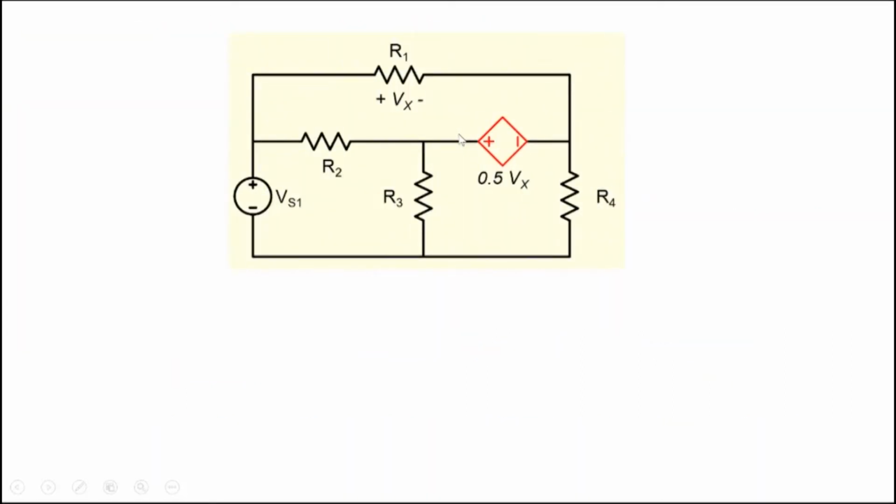Well, let's look at a case where we have a dependent voltage source. The dependent voltage source will make it floating, again by identifying these nodes and taking one as ground. So this dependent voltage source becomes floating, and when we have a floating source, we use the concept of a super node. We combine them together into a super node, and then we write down the equation at the super node.